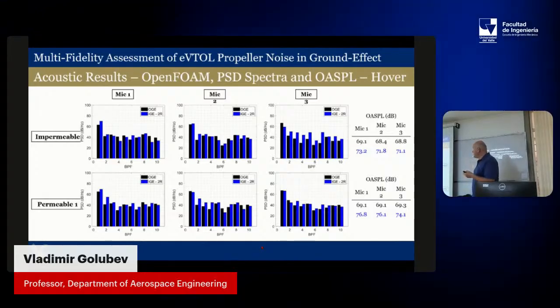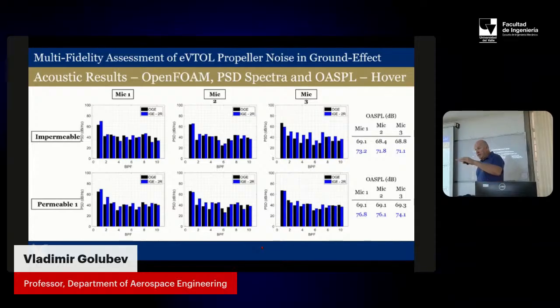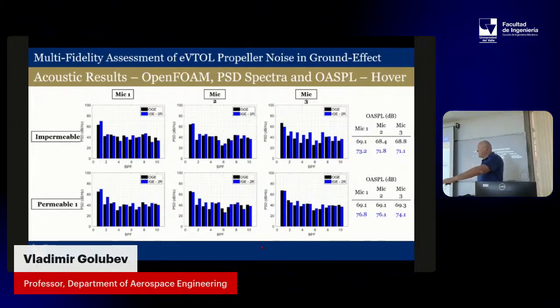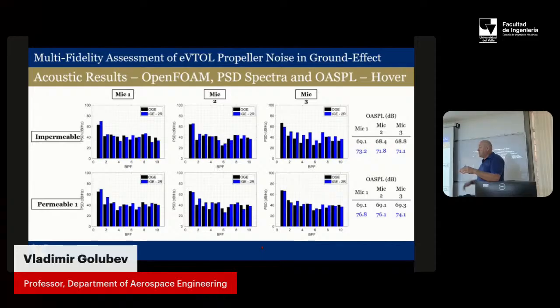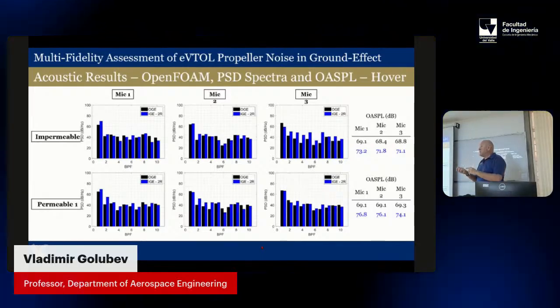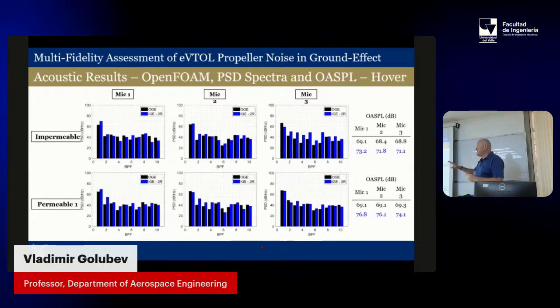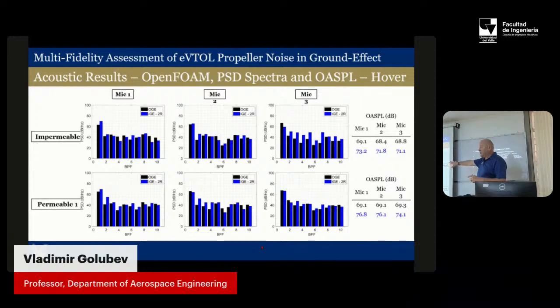Yeah, but then what happens? You have two mechanisms. Again, the loading noise is one thing, but near when it lands, that's why it goes up all of a sudden. There's interaction of the vortices, which bounce back and interact. So it becomes blade vortex interaction, which is most important. And that's what produces the major noise input. That's why it becomes like a helicopter.